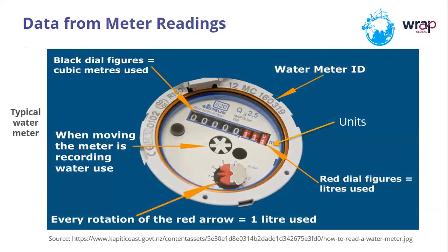If you need to take a meter reading at the start of the month, you will need to understand how to read a meter. Each meter will be different, but there are common features. There is normally a dial to show you if the water is flowing through the meter, and there will be a series of numbers that move forward as the water flows through the meter.